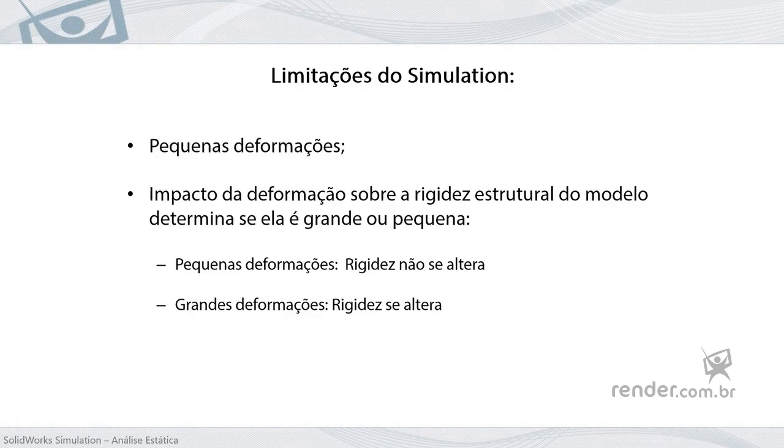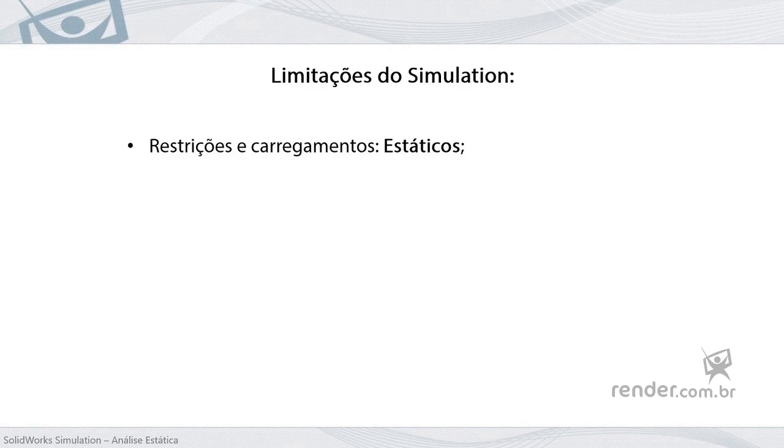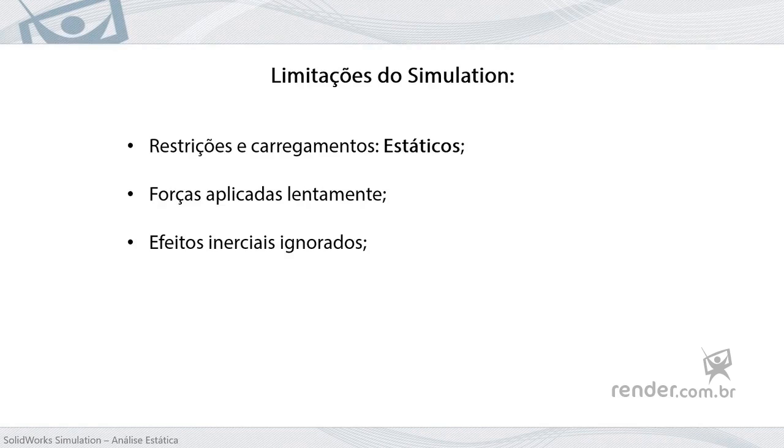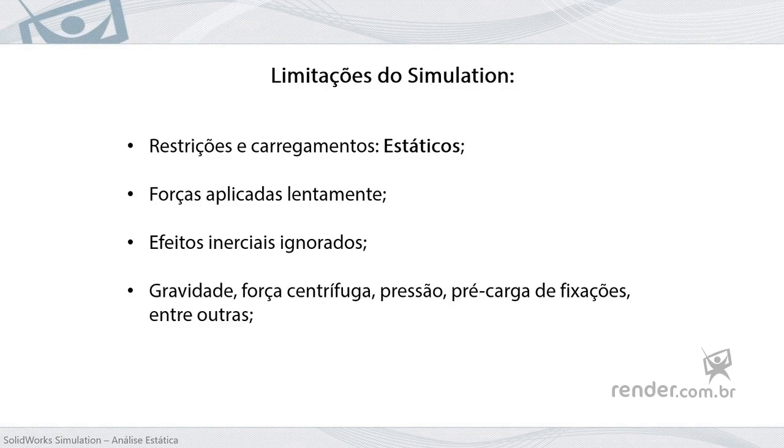The last limitation refers to loads and constraints, which should not change over time, i.e. they must be static. This condition implies that forces are applied slowly, so that inertial effects are ignored. Although a thorough analysis shows that every load changes over time, the static condition is correctly represented for gravity, centrifugal force, pressure, fastening preload, among others.